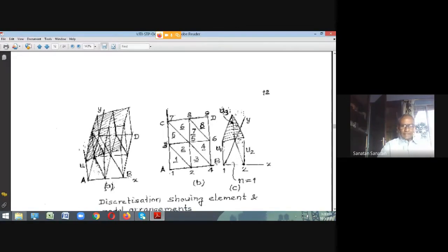So that's it. You see, as you reduce the size of the element, it looks like a plane surface. Then in that case, if you have such elements in the domain, 8 such elements, the whole surface will look like an assemblage of 8 flat tiles. Please note this. If I make the size of these elements very small, then the surface, which is doubly curved, originally looks like a small flat tile. Therefore, these surfaces will look like small tiles if the element size reduces.